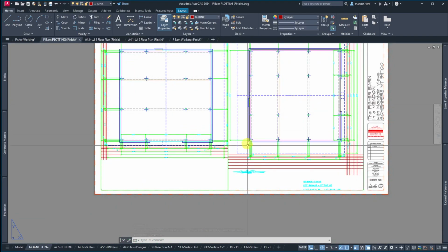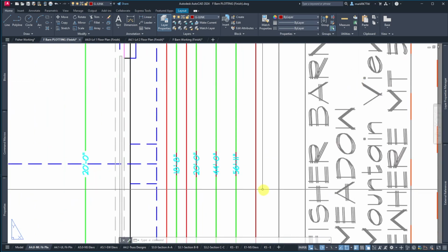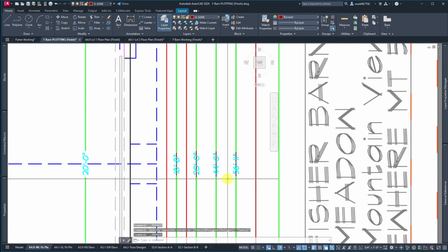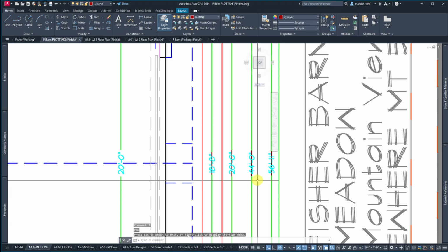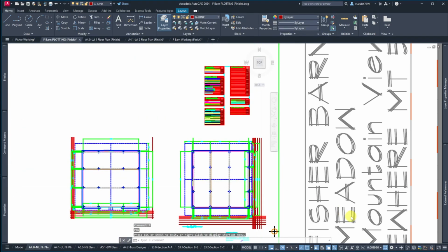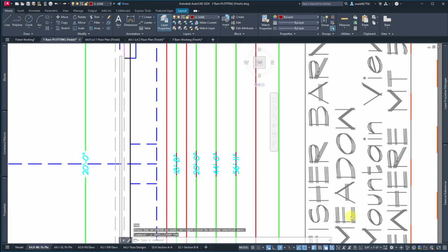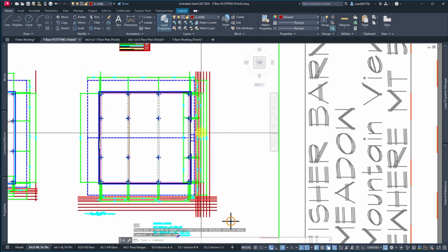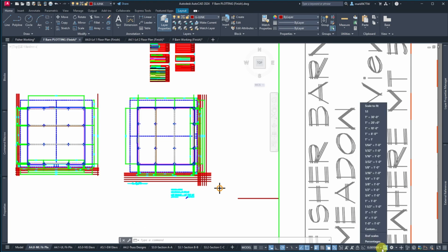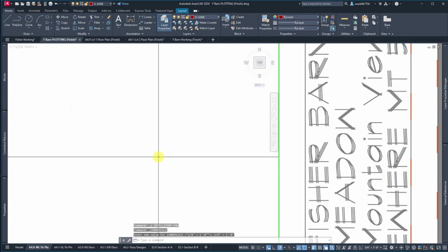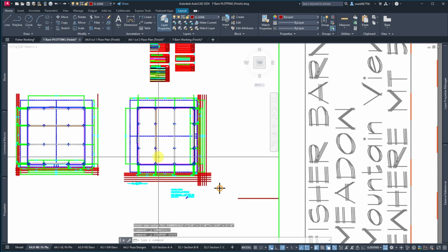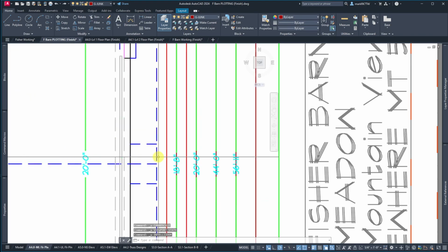So that's sitting there. Here I've got dimensions that I can pan over. So I'm going to pan this over to about there. Hopefully I kept that pretty, see, I just did the dimension thing. I'm going to hit Control Z to undo it. I'm going to do it again on purpose. Scroll out. See my number? It's supposed to be 1/4 inch. So you could select this, but it might not go back to the same point. See, it went off into space. So I'm just going to go Control Z, Control Z. I might need one more. There we go.